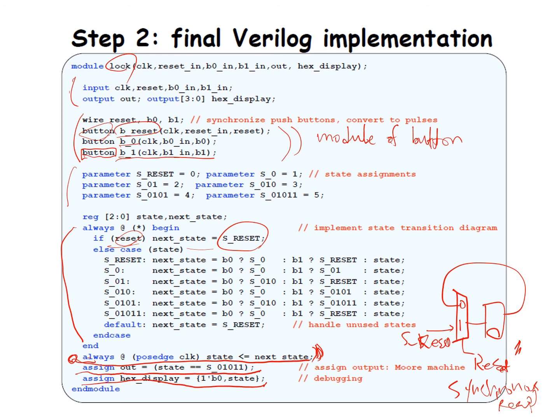This is a synchronous reset implementation. If you want to have an asynchronous reset for the state, you have to describe that inside this always statement. You can refer to the previous slides we learned before, okay?